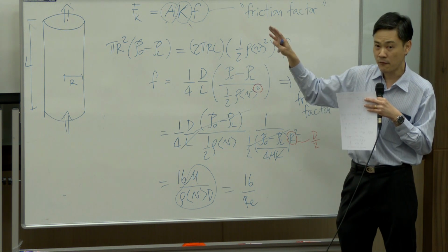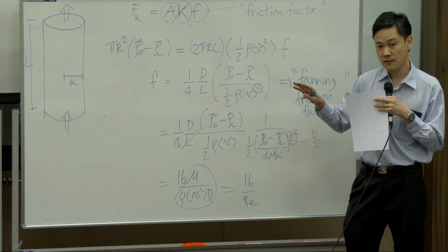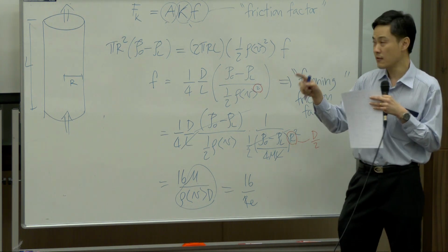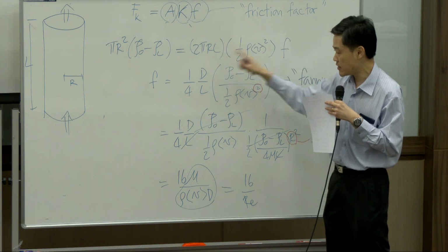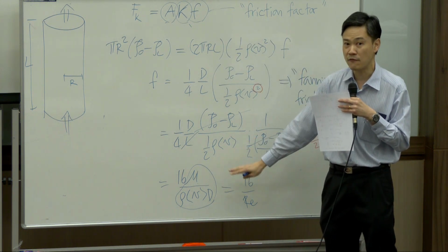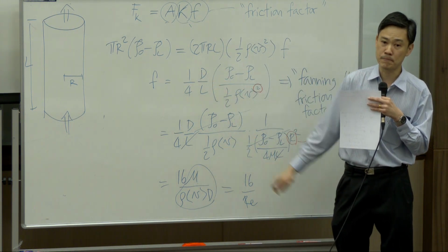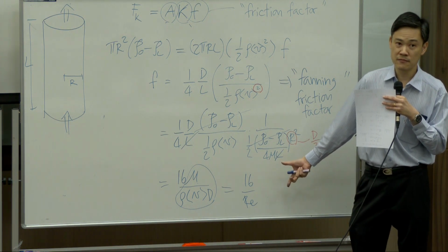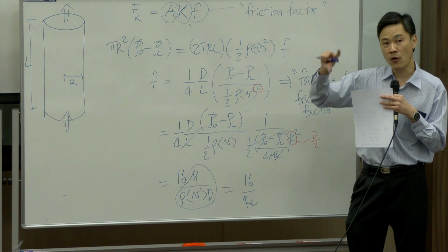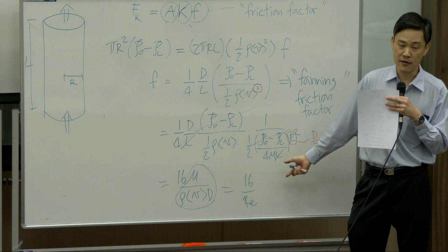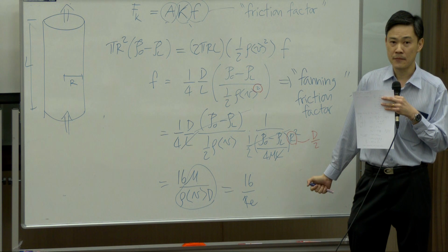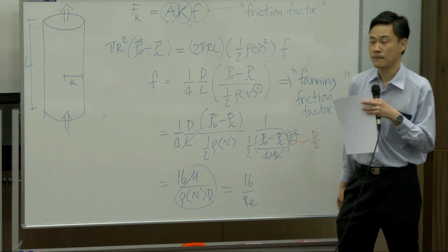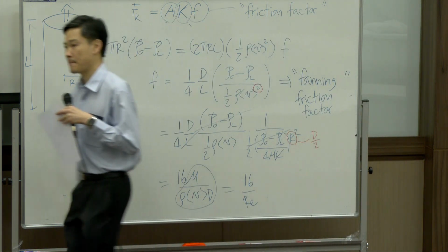From that velocity profile, find the shear stress. From shear stress, locate the shear stress at the wall, plug into this equation, and rearrange it again. You end up with an equation for that specific system. So that's how we calculate friction factor. Just like the friction factor in the elbow, that will be calculated in the same manner. Okay? You have used this without knowing the source. Now you know it. Any question?